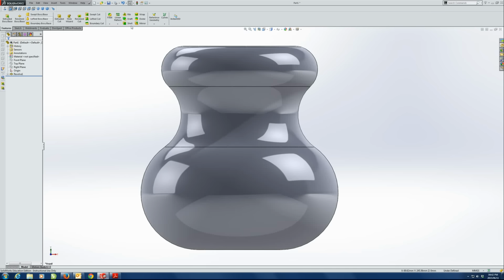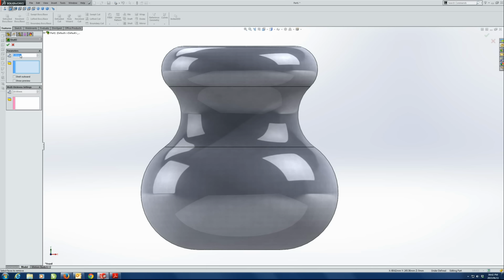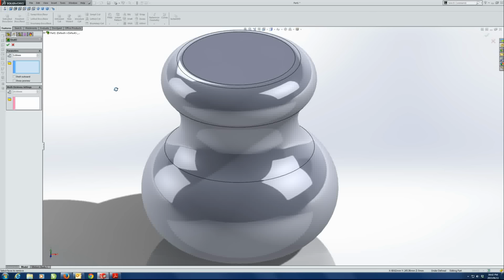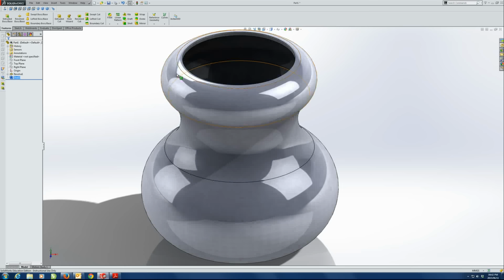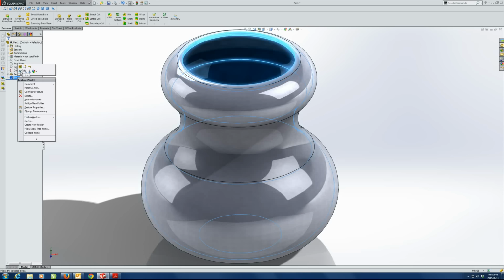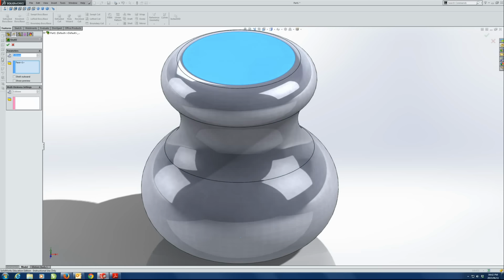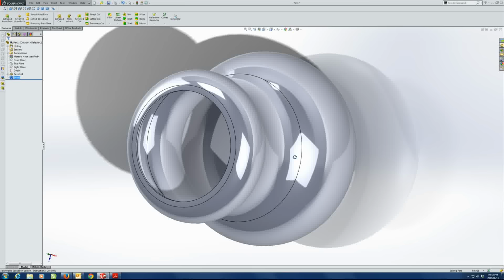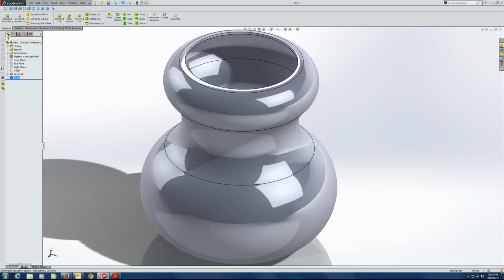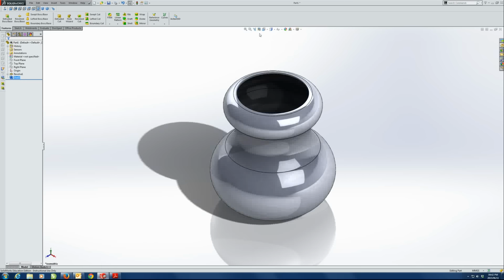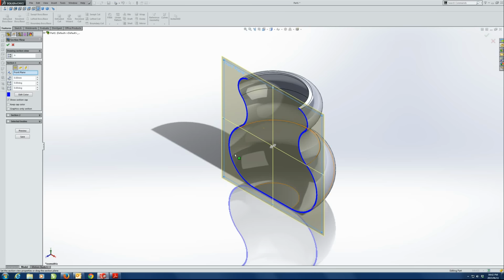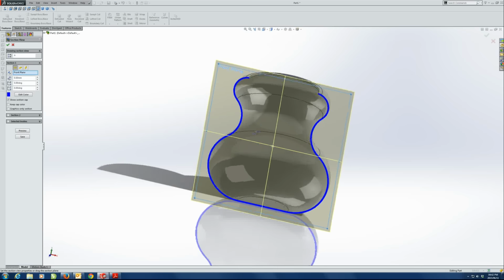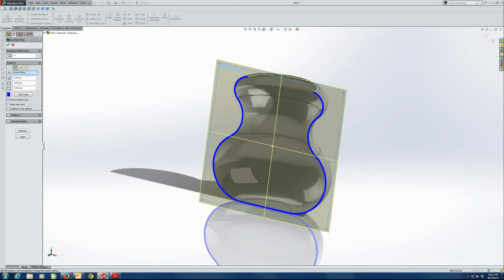Apply that shell. Okay, also changing this diameter over there also sometimes helps. There we go. Let's make that a bit less, maybe. See if we make it 3. Great stuff. Check it out. Okay, there is my vase. It's hollow. Let's quickly just cut this, and you can see it's shelled inside, and we're good to go.